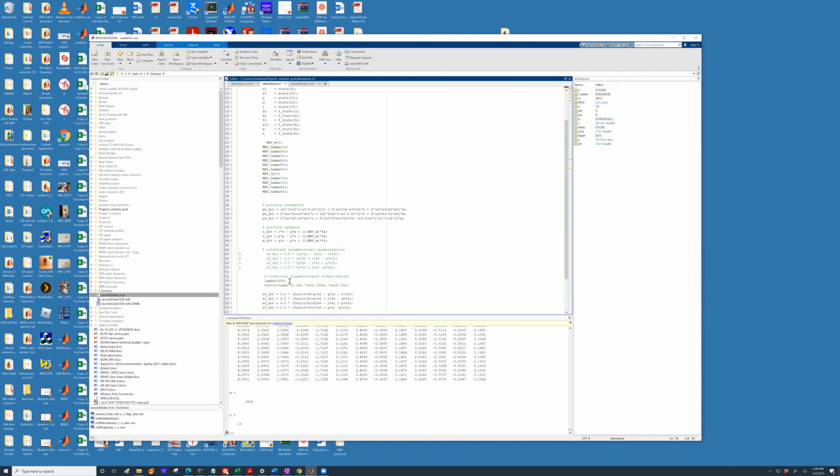But I want to look at the second set of equations where the rotational kinematics equation is normalized. So you can see here the value of lambda is 1000, and factor is nothing but lambda multiplied by, in the parentheses, 1 minus the norm of the quaternion.